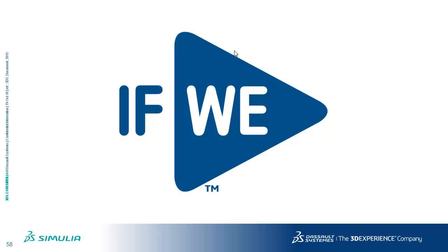So what about the through thickness mesh? Because I was seeing those through thickness meshes were nice and perpendicular, and you're not generally going to hit them. Ideally, that's what you want, because you want to base your nodal extraction on a reasonably good quality, reasonably structured mesh. But what we incorporate is essentially ray tracing with a cone. We put a ray normal to the surface of the weld toe, and there is a cone tolerance, starting at the weld toe and then expanding as you go through the thickness, trying to identify nodes along the way. And that's configurable, so you can make it as narrow or as wide as you want. I wouldn't advise going too wide, though.